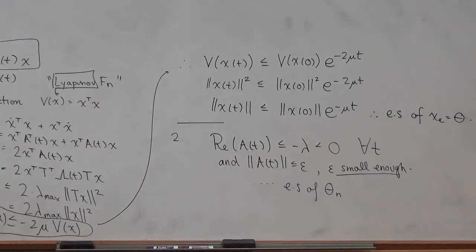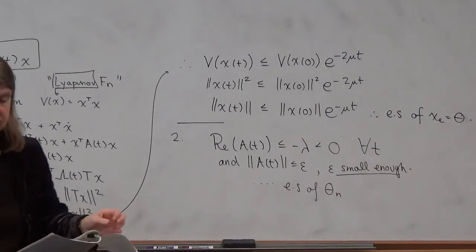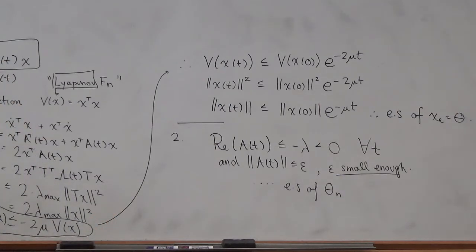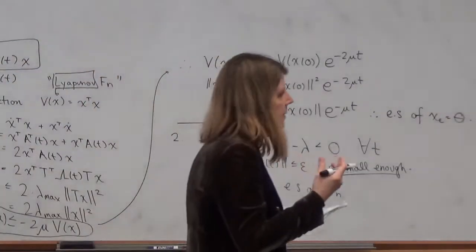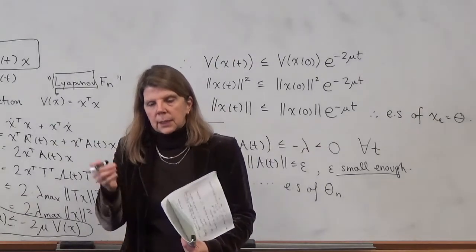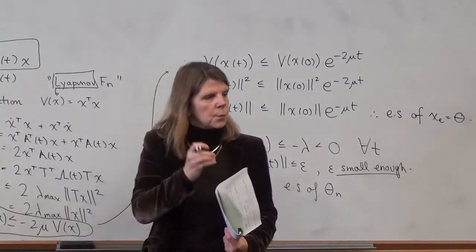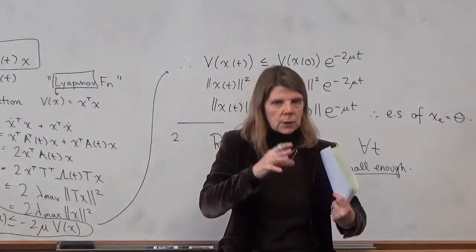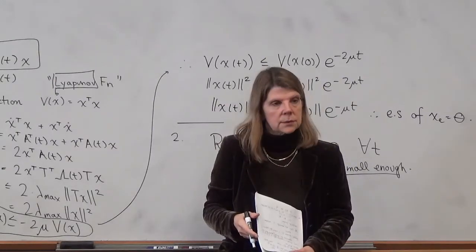Okay, so let's actually talk a little bit about Lyapunov for linear systems. We're going to focus on the time invariant case, even though this theory, Lyapunov stability, is more general. It applies to time varying systems. In fact, in the Khalil textbook, you have the full time varying theorem. And as I said, it applies generally for nonlinear systems as well. As I think I've told you twice now, it's one of the most portable techniques to come out of control theory to be used in other areas.